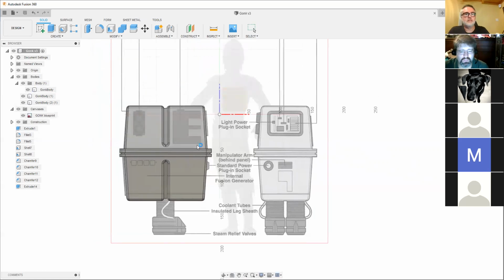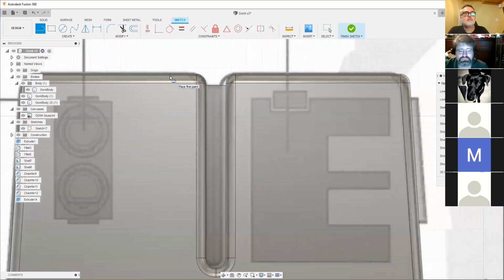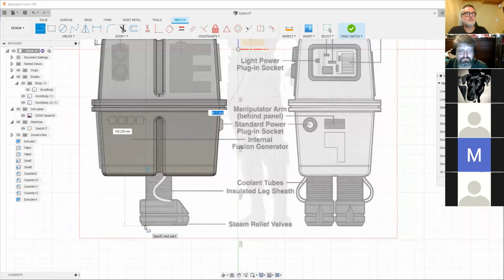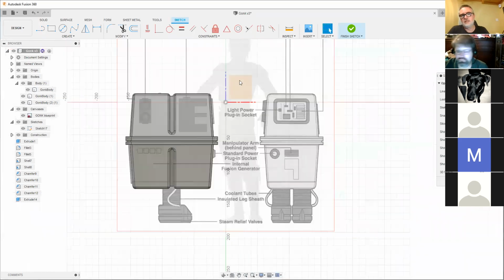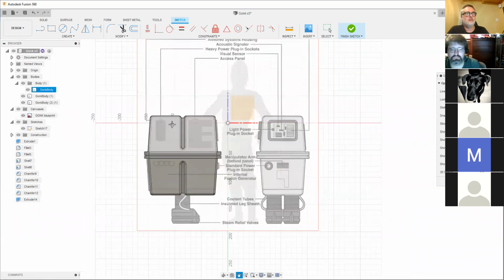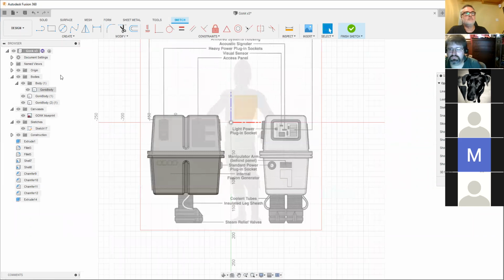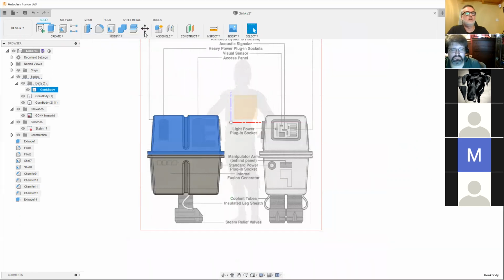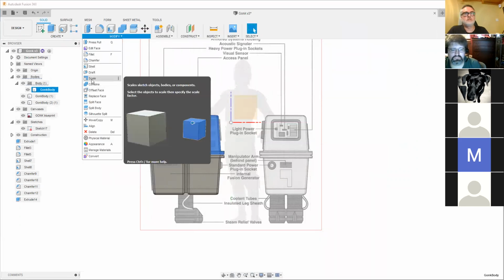So can you use the inspect tool there and see how tall that Gonk is? I've just gone into sketch mode and I'm drawing a line. So it's 198 millimeters. Oh wow, okay. So that's on this side, but obviously you can calibrate your canvas to whatever size you want, and for anything that you've created, you've got Modify, Scale, which allows you to resize it, so you can make things larger and smaller.